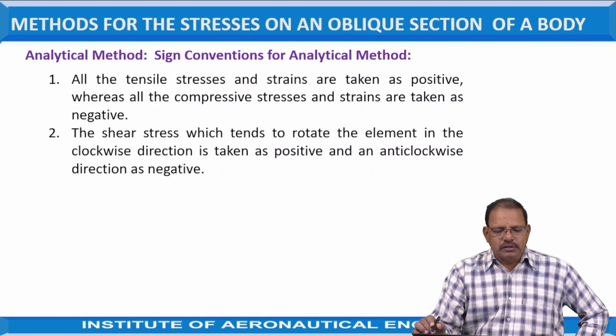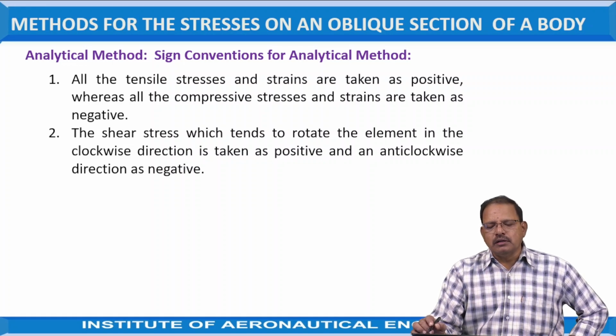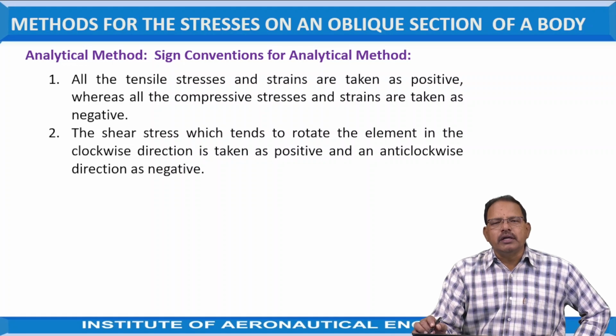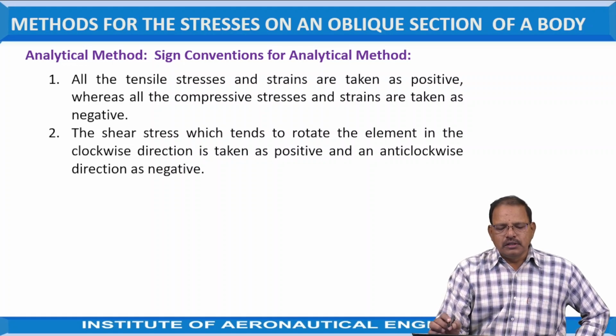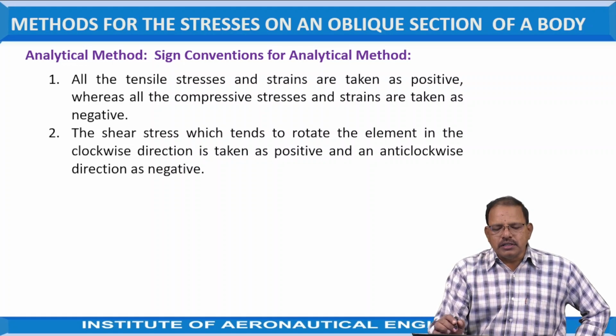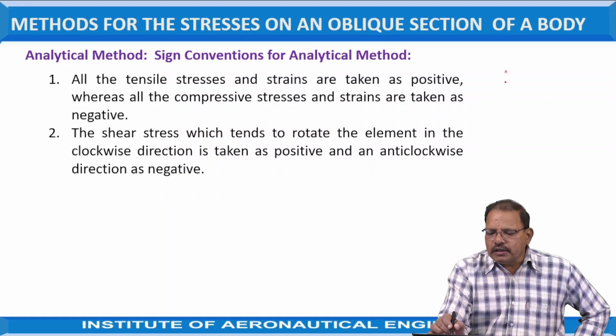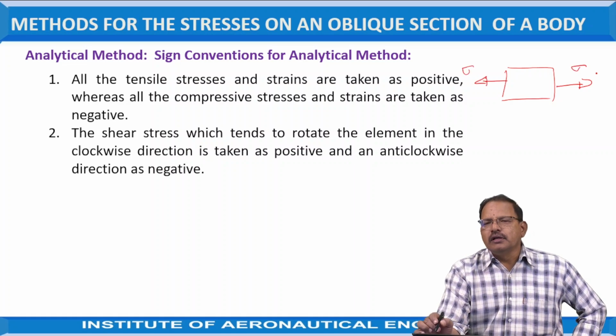Shear stress which tends to rotate the element in the clockwise direction is taken as positive and anti-clockwise direction is taken as negative. If I take the object here, this is a tensile stress along the x direction.